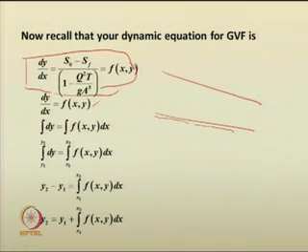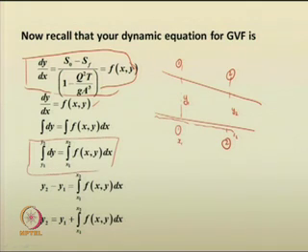Say you are taking a channel reach between two sections 1-1 and 2-2. You take two sections like this. Here, the depth is y 1, and here the depth is y 2. Say this is at a location x 1, and this is at a location x 2. Then the corresponding integration can be provided in the following form. That can be rearranged, and the solving is usually done in this particular form.